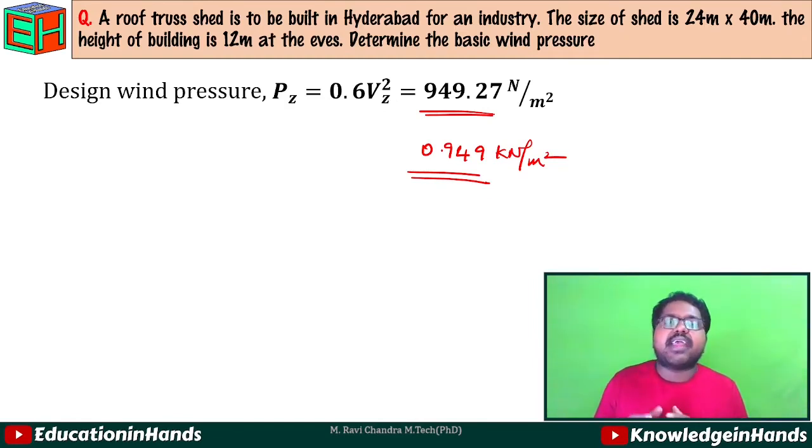In the same way, at the time of K3 calculation, there may be some variations in slope, so we can get the values of C and S differently. There, we need to work more on the K3 calculation. That is a kind of complicated problem. We will see such problems in the design of roof trusses, where we will discuss these wind loads and their calculations again.